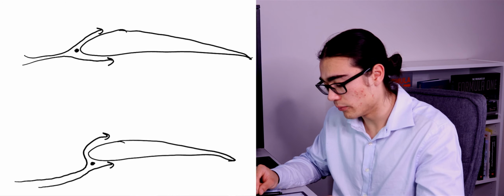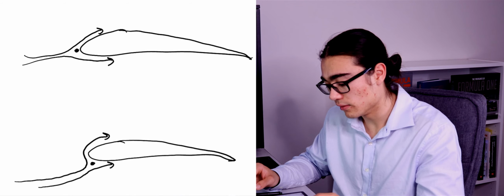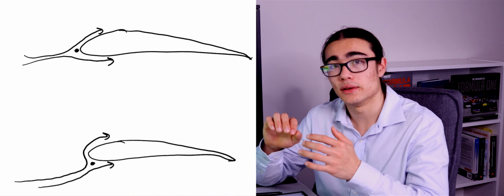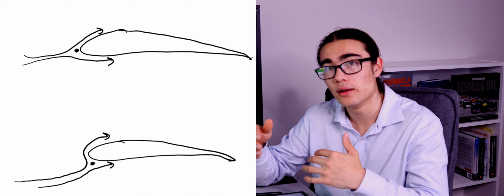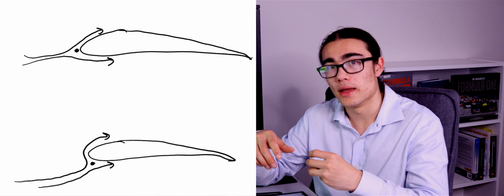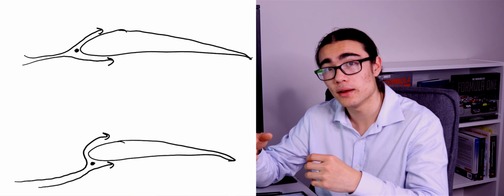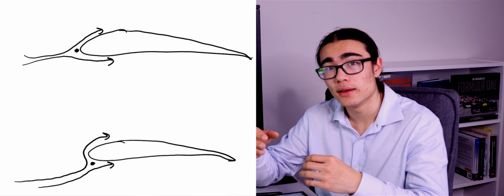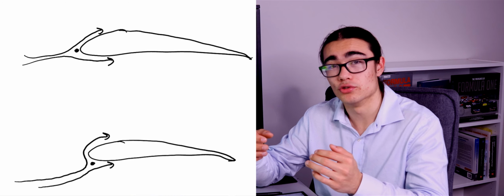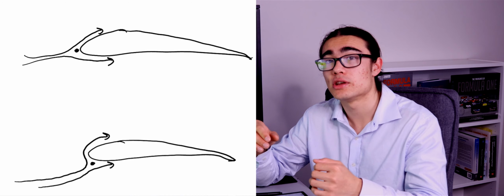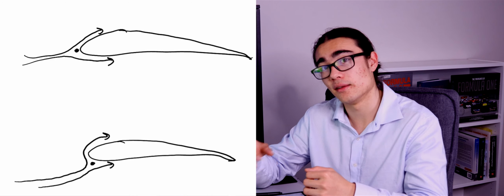Now, the first thing to note when we concentrate on the underside surface is that when the stagnation point is lower, you can effectively increase the angle of attack very slightly, dependent on how much lower it is, of the whole airfoil. This is because we're ramming more air into the bottom side, because our onset flow vector is effectively at a greater delta angle to our original airfoil. So without changing the geometry as such, we're still actually changing the angle of attack. That's something we have to note.